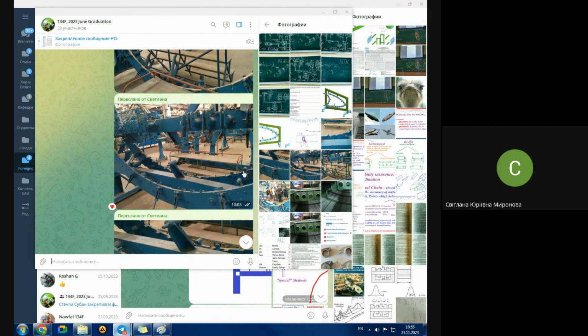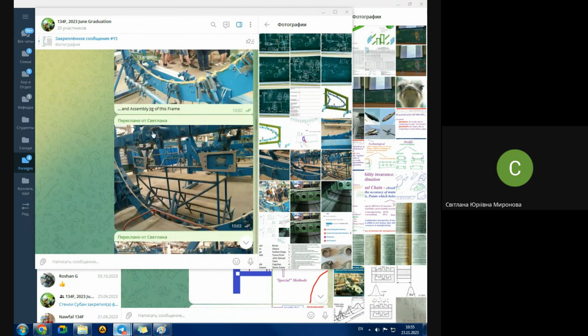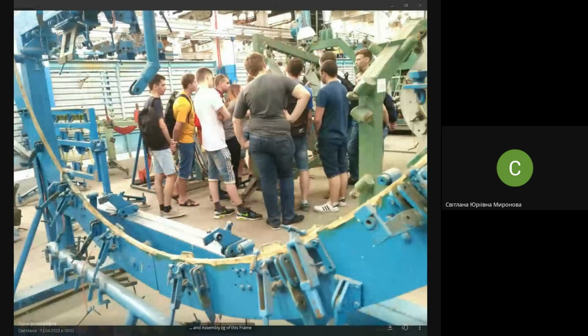I hope it's visible to you that the frame of the jig, those beam-like elements, are also assembled. They are not a solid unit made from one piece of metal. They are welded, rather roughly, from pieces of standard extruded profiles. It may be T channels, it may be C channels. You see some different jigs here, and they all consist of C channels welded to each other, something like a beam with an inner cavity.